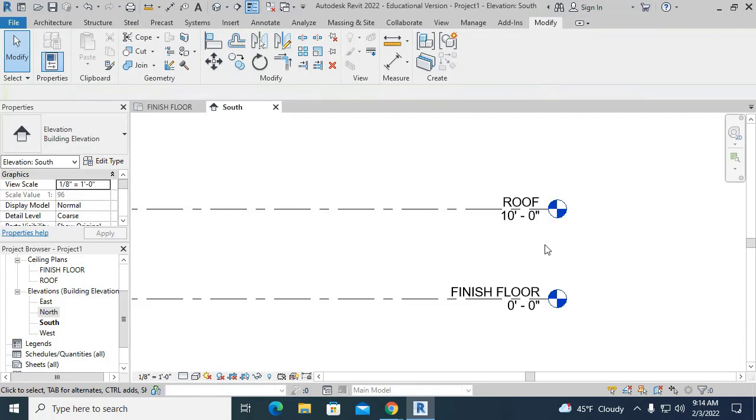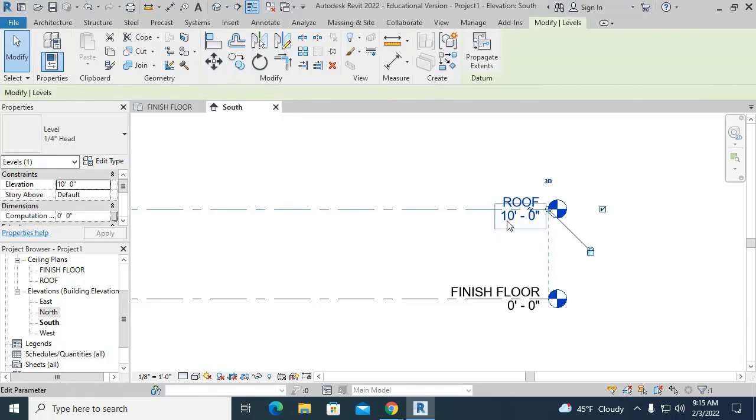Okay, by the way, I'm going to go above this. What I'm going to do this time, though, is I'm going to click on the bottom, on the height. It says 10 feet. Click on the bottom. It's going to have the rectangle around it. Click on the 10. You should see the 10, right? And you can modify the height, right? Okay.